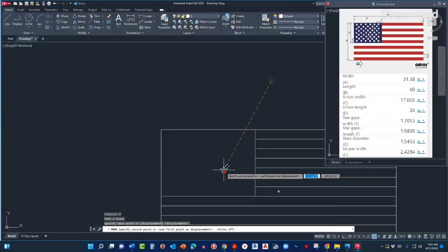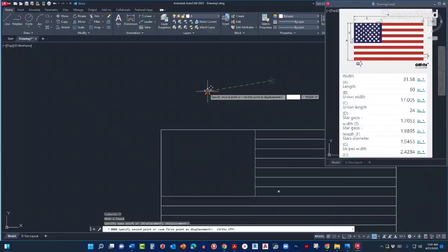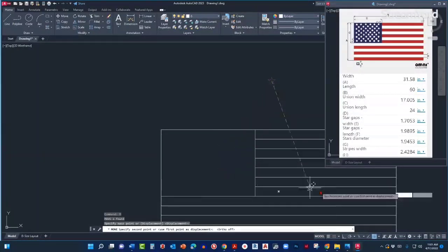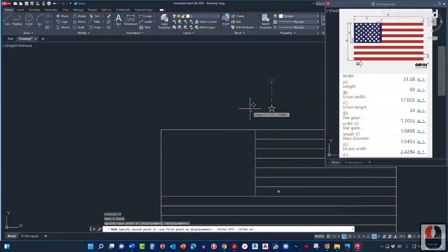Now, that means you have to turn the ortho mode on and off every time to move things? No, not really. Let me show you how. So let's turn it back on again, because ortho is always useful to have on all the time. In order to move freely, we can hold the shift key on our keyboard.